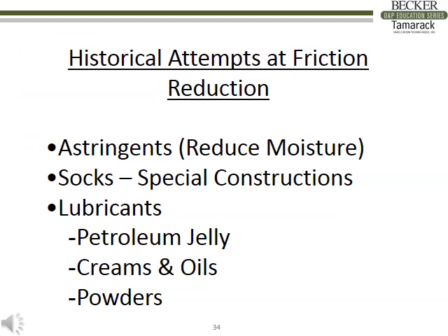Historically, there have been other approaches to limiting friction shear forces on the foot. Astringents help to keep the skin and sock dry. That is useful because moisture tends to increase the COF of most interfaces. There are socks knit in a way that produces a layer of loose loops under the plantar surface of the sock. That layer of loose loops is able to absorb shear displacement better than ordinary knit socks. There are also socks knit with a percentage of the slippery PTFE fiber.